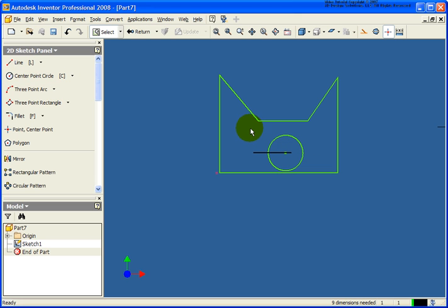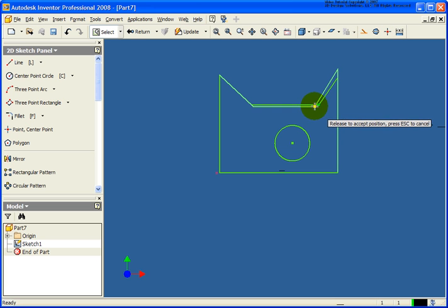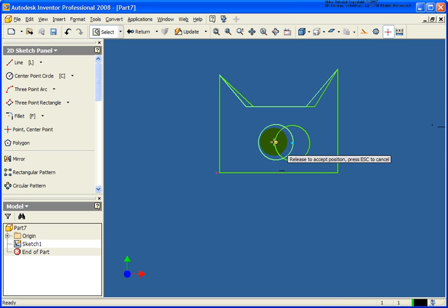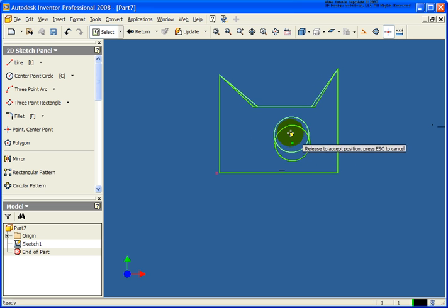So now I'm just going to press the escape key, and let's talk a little bit about dragging. So now as I grab that point and grip edit that, which is very familiar to AutoCAD users, the circle is staying exactly at the theoretical intersection. As well, if I move that circle, the lines move. So there's a definite relationship that is tied to that.